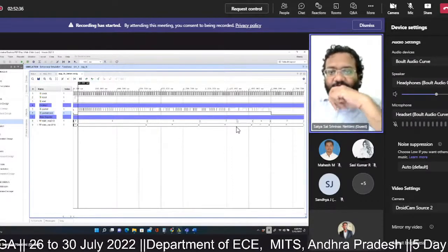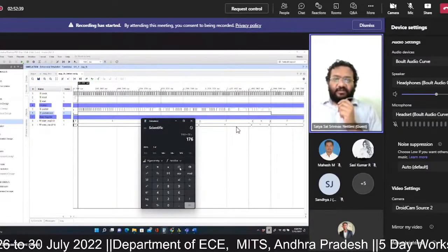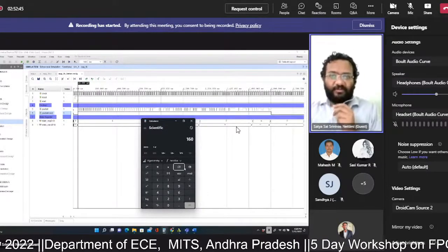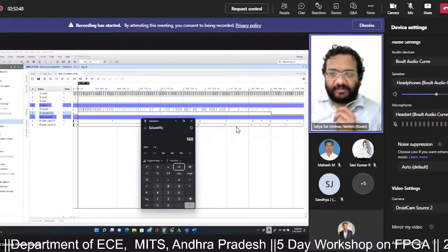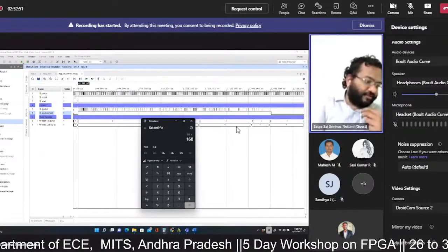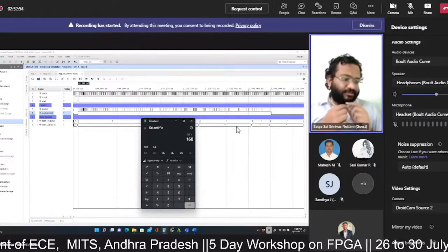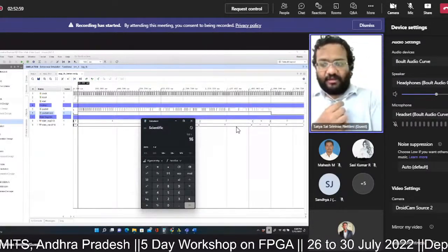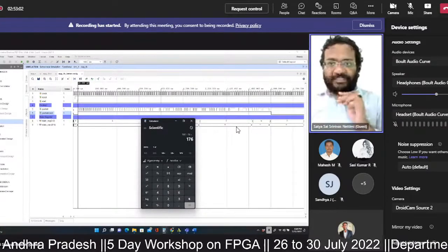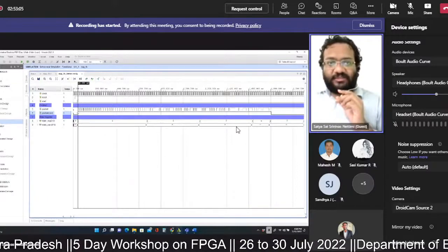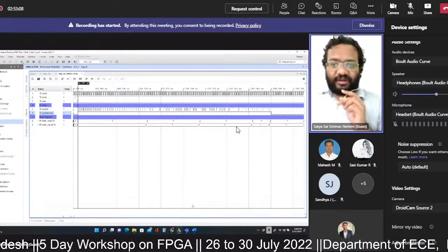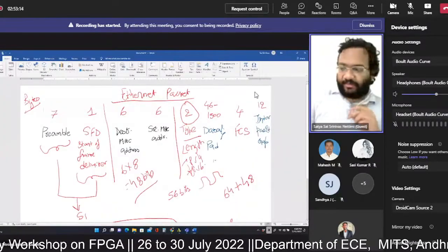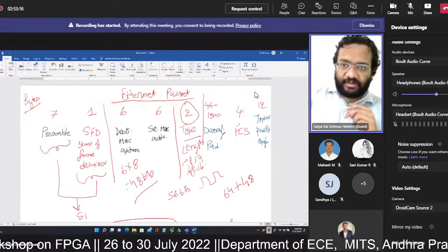Earlier, up to the destination and source MAC address, the total number of bits that we received in the Ethernet frame is 160. Now for the type field or length field, that is 2 bytes, right? 2 bytes into 8 bits is 16 bits. So 160 plus 16 equals 176. This matches the total number of clock cycles. So I think we have partially generated the Ethernet frame up to the type field. Up to the type field has been completed.